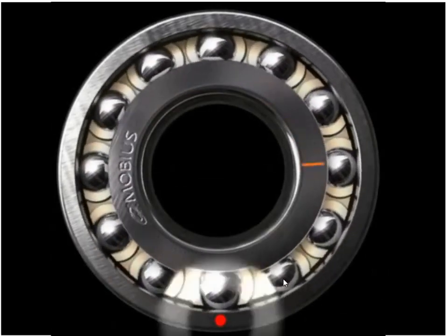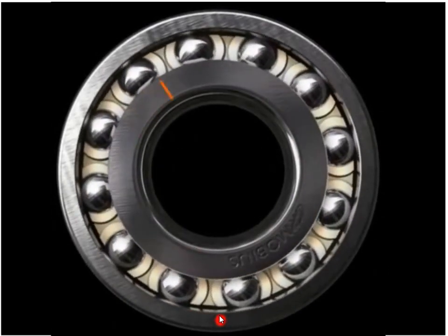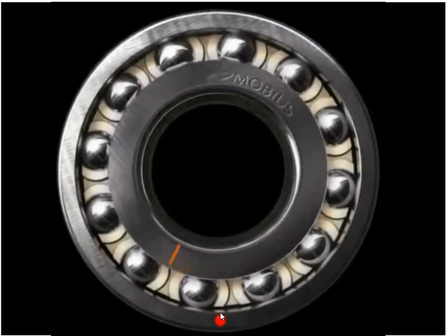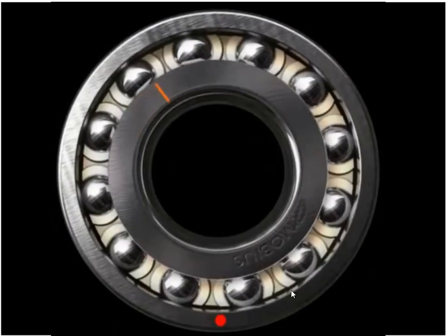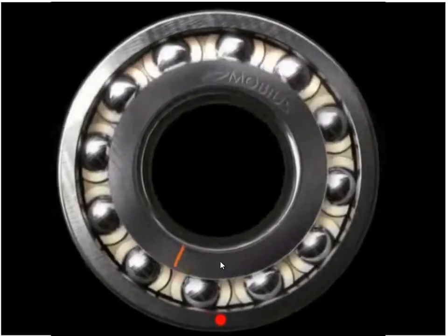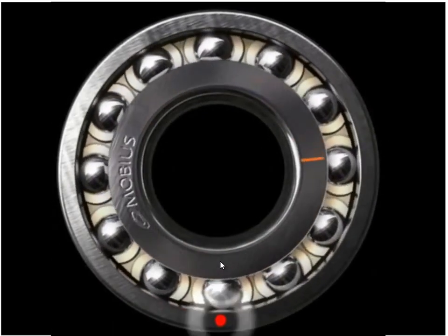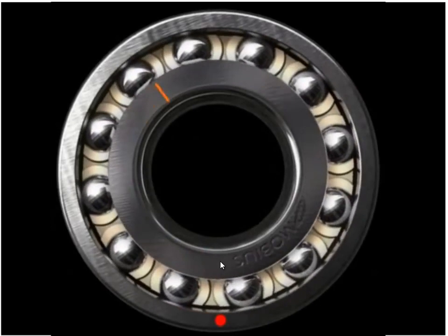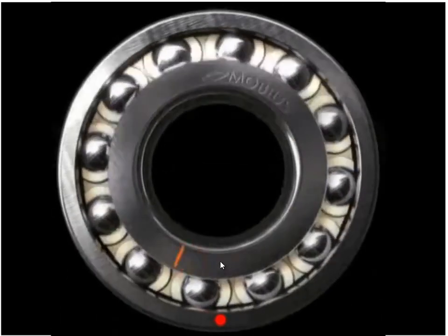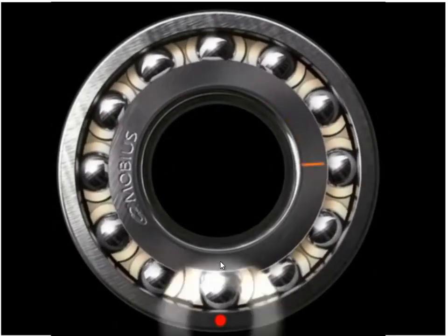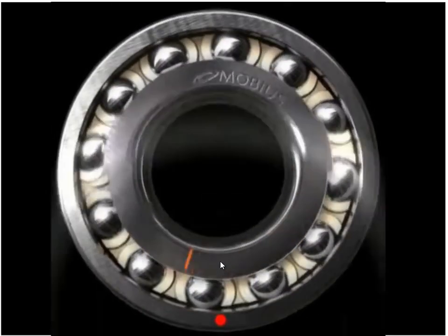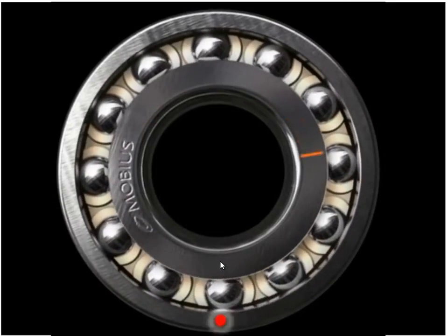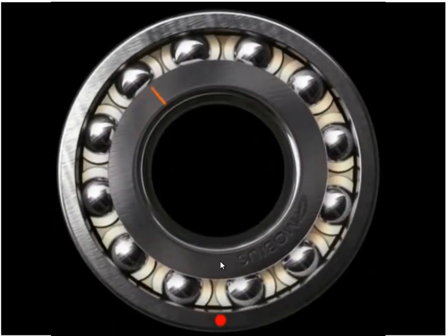But when the rolling elements come along and make contact with the spall or the crack or whatever is sitting there, we get an impact, and you can see these white waves rushing out. That's called stress waves or shock pulses. If you take any two metallic objects and clack them together, you put a little short stress wave through those two items, and we can detect that.